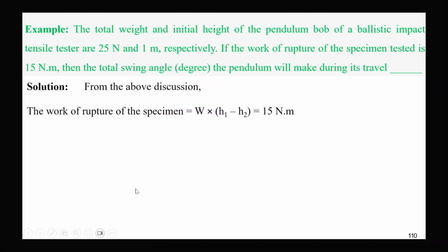So the work of rupture, we know, is weight of pendulum times h1 minus h2.